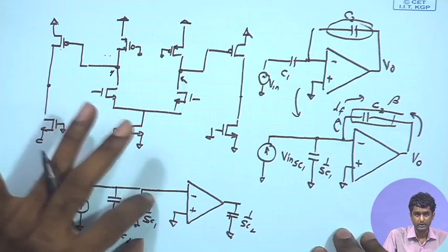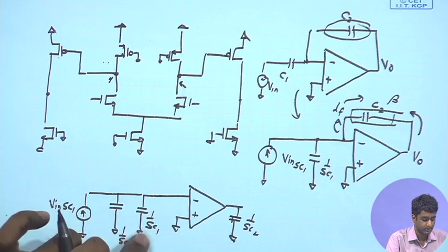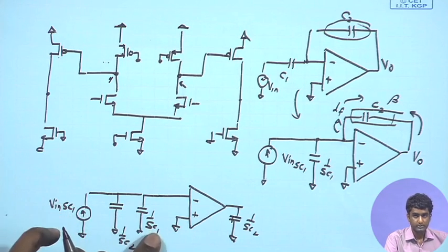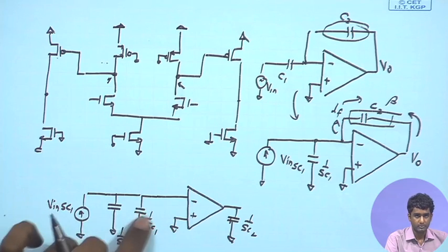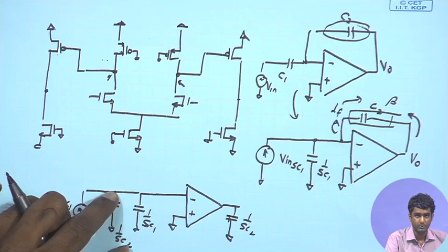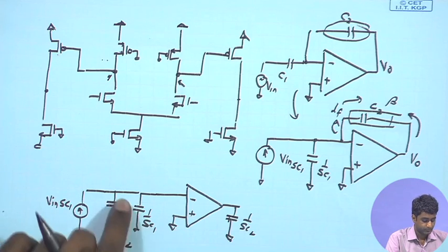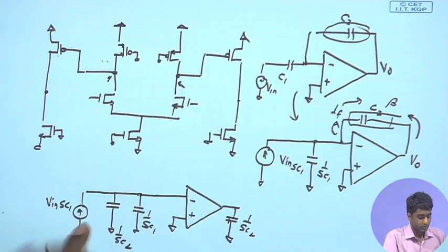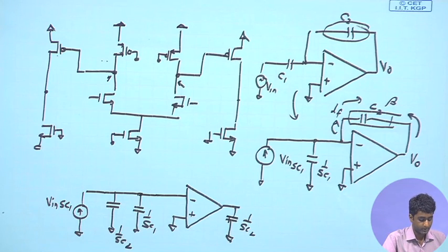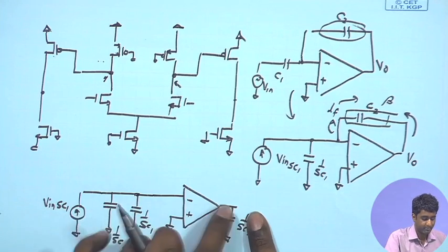So, in terms of impedances, if I look at the complex impedance coming because of these two capacitors, the C1 is dominating, and therefore, we will assume this to be the dominant component. This may not play an important role with respect to C1, and therefore, if we look at the overall voltage signal developed at this point, for the open loop, we need to find out the overall A beta.